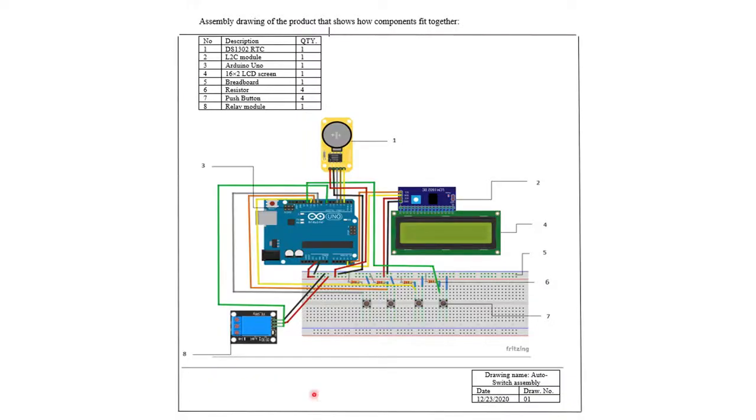For example, we use the Arduino board rather than an integrated circuit, a battery rather than power plug, and an RTC module to configure the time, without forgetting the use of a combination of both the screen and push buttons in order to interact with the user.